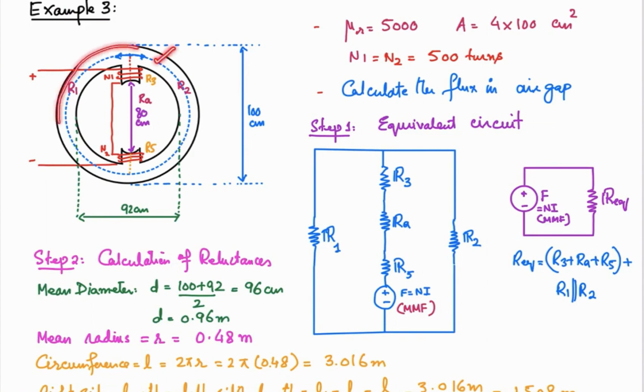So, continuing from there, a magnetic circuit is given to us, that is shown over here. It's a circular core having two pole shoes over here, and a winding is provided over these pole shoes to establish the flux in this structure. You can say this is the stator part of our DC machine, and the rotor part will be there in the center of that one. So we are going to analyze the outer part of the DC machine, that is the magnetic circuit.